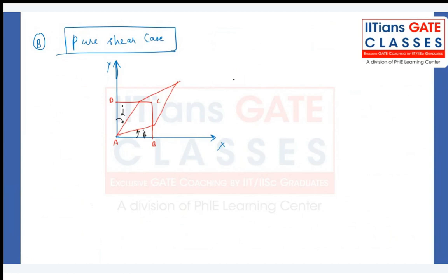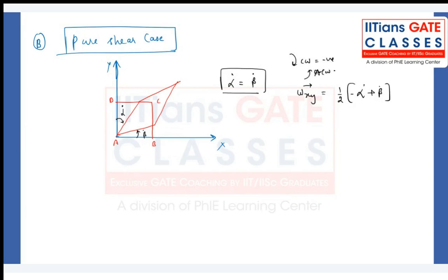Here what is happening? Alpha dot is equal to beta dot. Don't write minus beta dot, plus beta dot. Both are rotating equally, but in the opposite sense. Then tell me, what is omega xy? By definition, it's the average of those. But beta dot will be positive and alpha dot will be negative according to our sign conventions, because alpha dot is clockwise, and clockwise we have taken negative, anticlockwise positive.